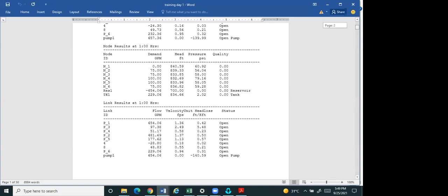No, I think the tank volume is fixed, but what is changing is based on what you want to see in the tank. The tank is acting as a node, so the tank can only change color based on what is happening in the tank, the pressure at the tank, at that point. So it is not giving you whether it's over dimension or under dimension. It's you that will do that, but it will be giving you the pressure at the tank based on the height. You know, the tank has a height of 20 meters. So as the water is dropping down, the pressure is fluctuating.